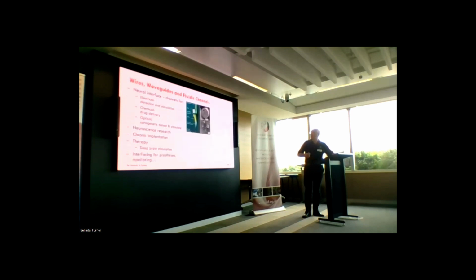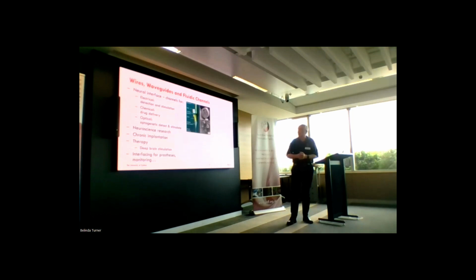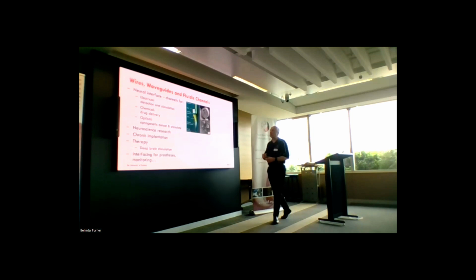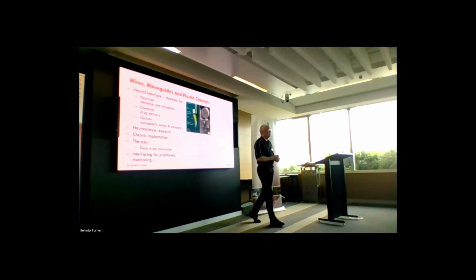Okay, so having started putting wires into dielectrics and made some cute metamaterials, we thought of something a bit more practical that we can do with this. We started looking at the possibility of neural interfaces. We've got some colleagues working in optogenetics, where they transfect cells so that they're optically sensitive, and being able to get in a light signal and an electrical signal for stimulation or detection of neurons seemed to be a cool idea. So we made this thing here, which has a central waveguide and then 4 sets of 4 electrodes embedded in it.